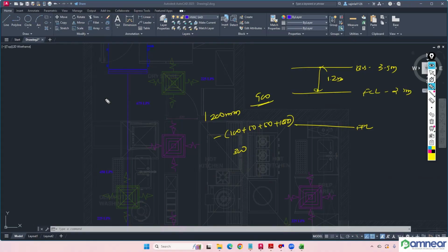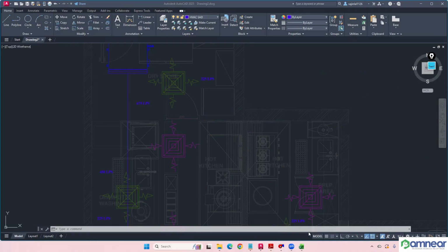So even up to 900 mm height is permissible, right? With acoustic insulation allowances, 900 mm internal height is permissible. This 675 is a low flow rate only. We don't want this 900 mm height and all. So the maximum permissible duct height as per this false ceiling minus allowances is 900 mm you can provide. We don't want that much. So I will try to make this aspect ratio 1 if it is possible. Whenever it is possible, try to make it aspect ratio 1. So 675 liter per second, I am going to size it.